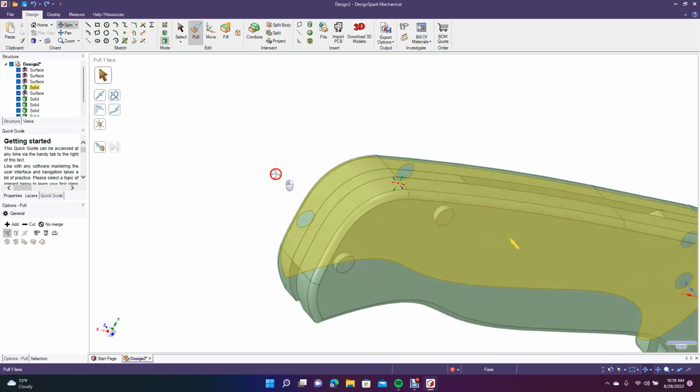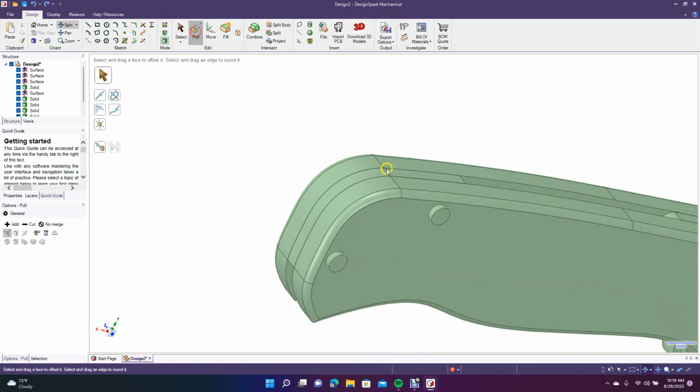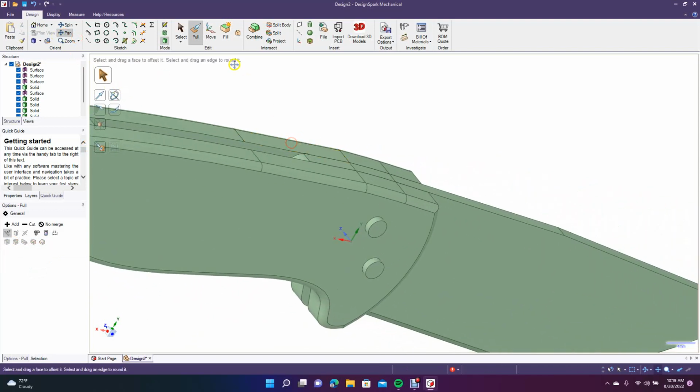We just need to do the around the back side here. Let's pull these. Change to chamfer. 0.5. Do the same on this one. Chamfer 0.5. Pan over and get these two right here, 0.5. Oh, not fillet, chamfer. So I'm going to change that. 0.5. Chamfer 0.5.